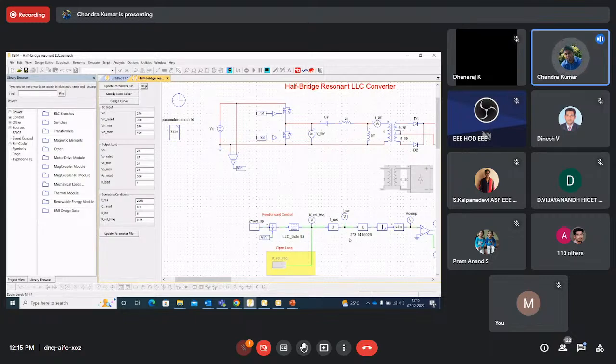Okay, one more. So probably I'll answer. It is because of the switching losses. When you go for buck-boost, these are hard switchings. When you go for these resonant converters, it's basically soft switching. Basically, you reduce your switching and conduction losses. That is the importance of why they have the resonant tank circuits. That is what you see here.